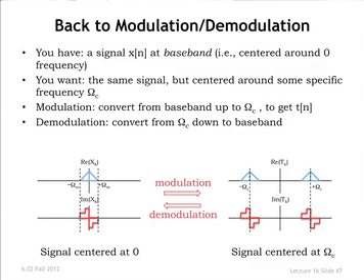You've been allotted some part of the frequency axis to do your transmission in because someone's told you perhaps that the medium that you're going to use can only transmit in that range, or the FCC has decreed that you're only going to use that region. So you want to send that signal somehow in another frequency band. So modulation was the process by which we converted up to some carrier frequency, and then demodulation was what you did at the receiver to get back down.